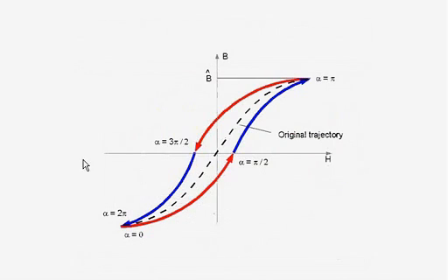The other nonlinear property I had to do, and I go back to this one. There are two ways to find the core loss in the ferrite device, which I needed because I had to couple the core loss into the thermal solver to see how hot the ferrite gets.